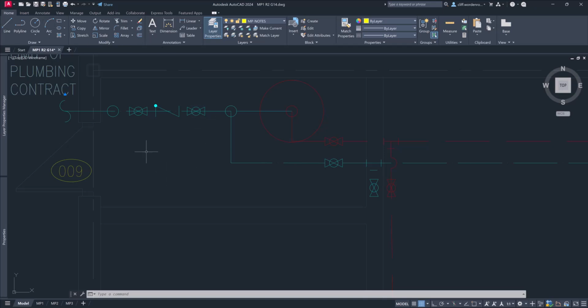This is the water service entrance, and it's up on Brightspace, so you can grab it and put it in. What we're going to do is size this line here. That line is the one that comes from the city, the one that supplies water to your building.